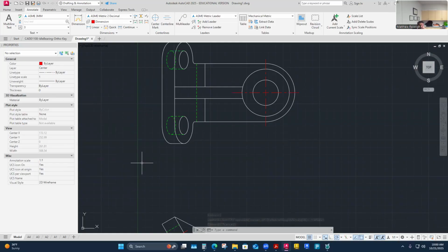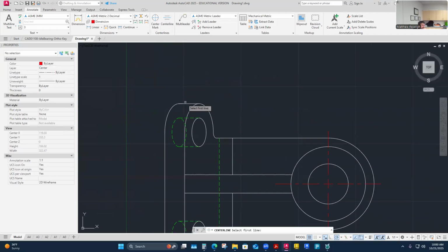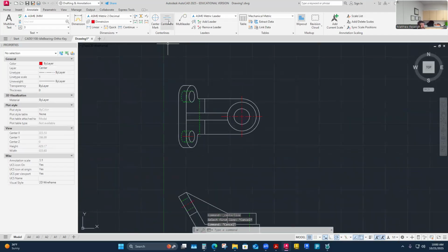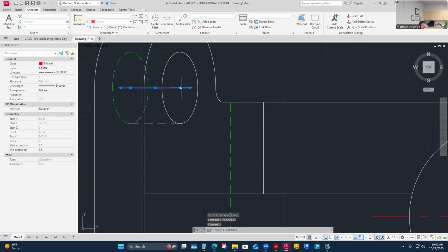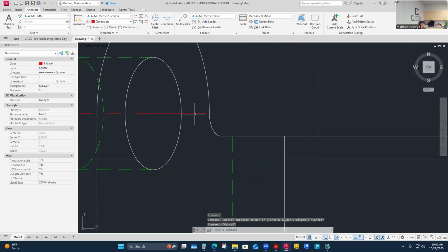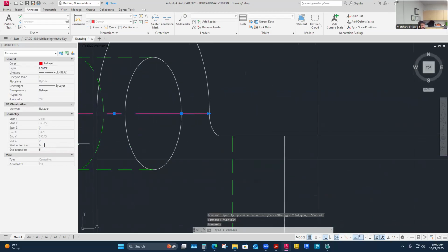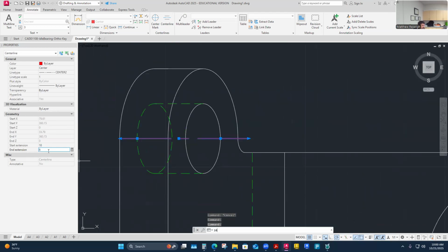You have to use center lines. Yep, yep. So I could do a center line and use these two hidden lines for my center line like this. That's probably the way I would start it. And I could do one and then copy and paste it over. But yeah, I still use my center line command and use maybe something like this. And then I'm going to pull this through to here, probably initially through here, and I'll do my extension, that's 6. Those could extend definitely to a dimension potentially. So where I'm this close to going through both sides, I feel like I'll probably extend that a little bit further. I don't know, like 10. I think just because I have some lineup going on there, I'm choosing to extend my backspace.